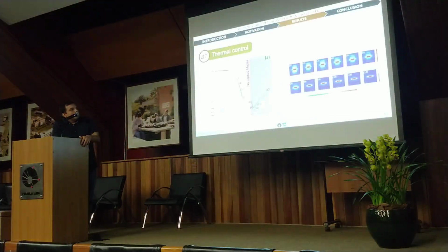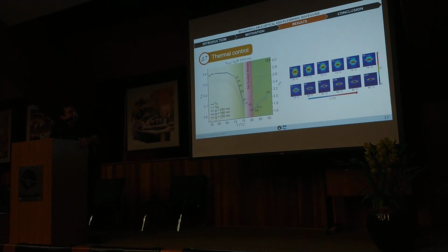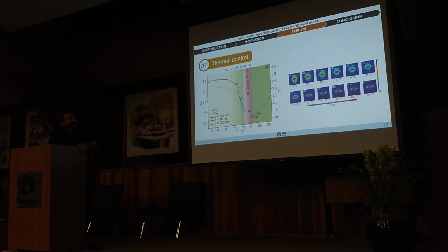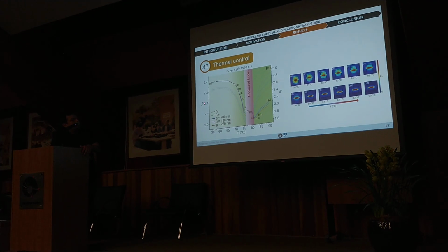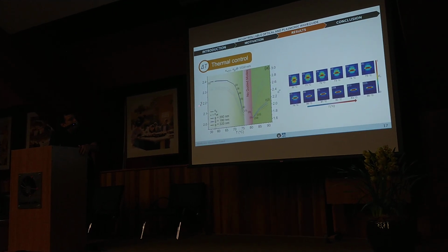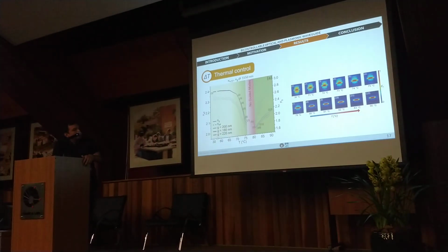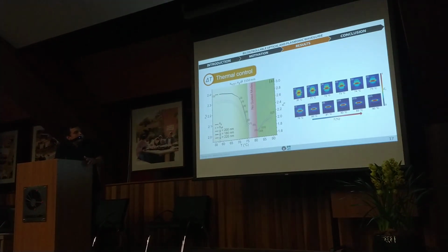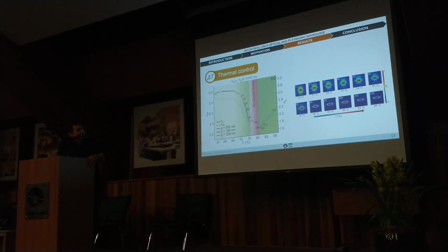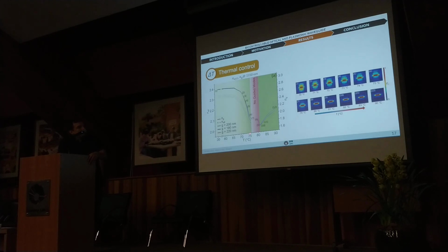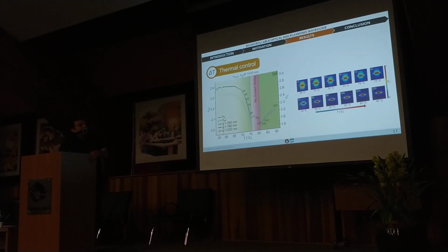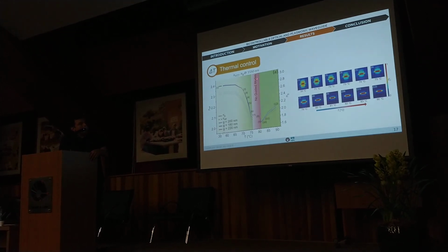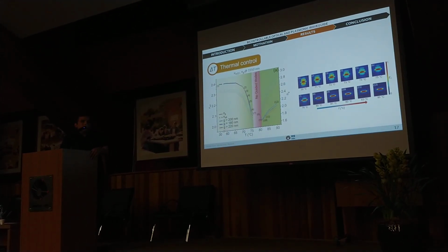Here in more detail, I highlight some points of this graph in this transition. You can see here the effective index of the mode which propagates through the waveguide, and the group index of the mode. Another interesting feature of the waveguide is that from 76 to 81, there is no mode propagating over the waveguide. So you can have a band gap here at 1.55 micrometers.